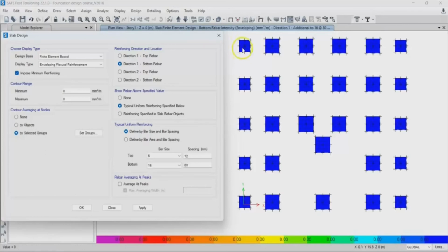So if you're having a mat foundation, all you need to do is build just one long formwork in the y direction, and also one long formwork in the x direction. Then you repeat the same in this direction and also in this direction. So it's going to take less time, and it's going to cost you less money, right? So that is also one of the reasons why we provide this 50% threshold rule. And also one of the main reasons is because of the overlapping soil stresses.